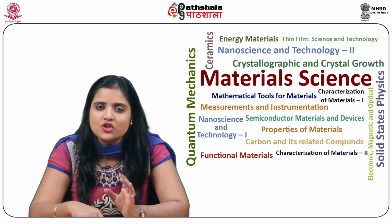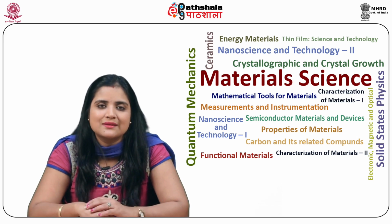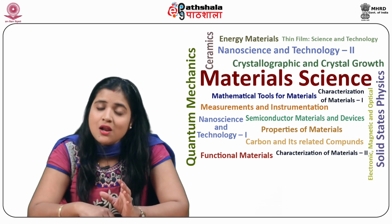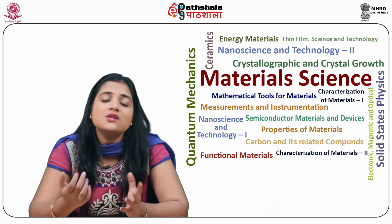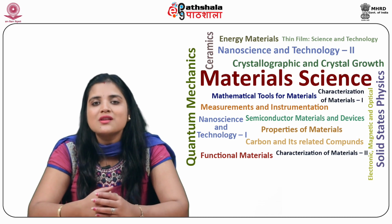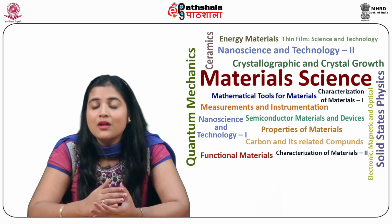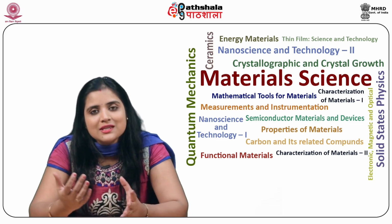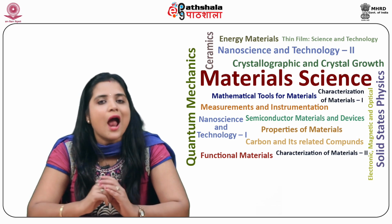A 4-bit digital output requires 15 comparators. In general, for an 8-bit digital output, which is preferred for most applications, 255 comparators are required. The circuit in this case becomes very bulky, complicated, and expensive.